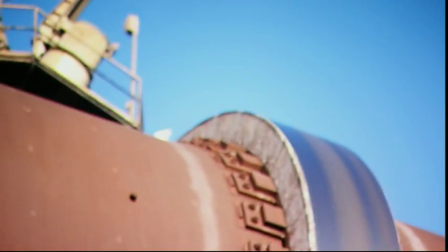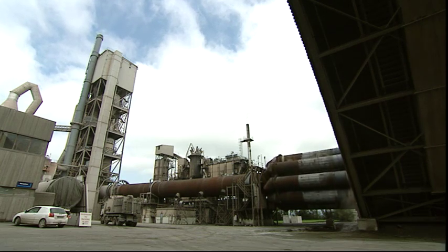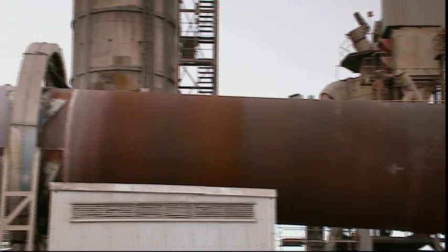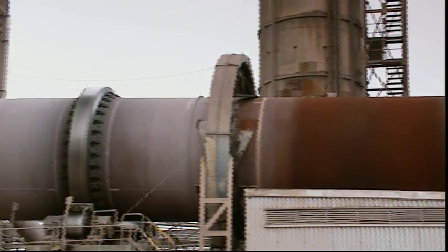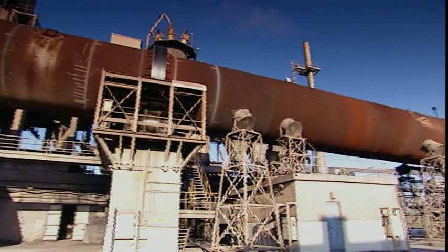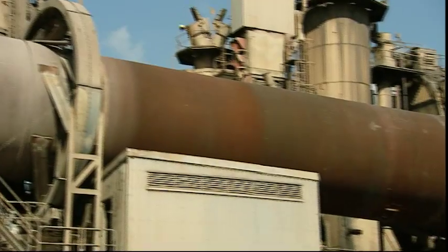The hot gases from the kiln outlet are utilised to preheat and partly calcine the kiln feed in a tower of heat exchange cyclones. The rotation of the kiln conveys the powder towards the firing zone. Formation of calcium silicates, which are the key components in cement, is completed as the molten material reaches 1450 degrees centigrade. The output of the burning process in the kiln is cement clinker, which must now be cooled.